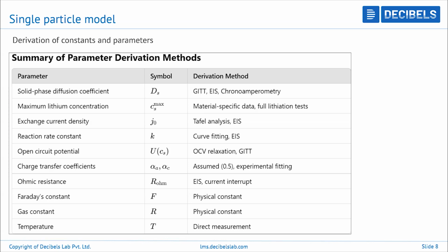So there is a lot of material testing that has to be done, and much of this data is reliant on three types of cell testing. The first one is what is known as pulse based testing, where you are subjecting the lithium ion cells to multiple pulses, and you can see that listed over here, GITT.